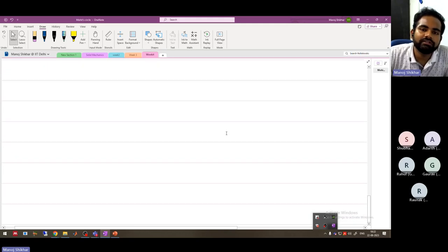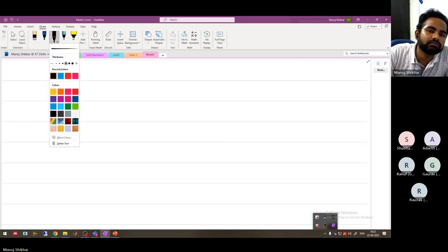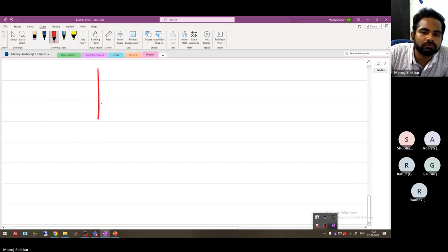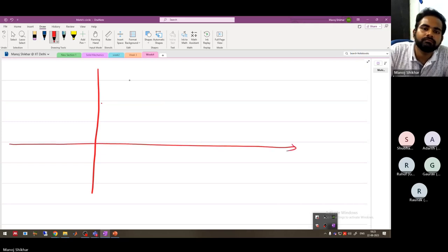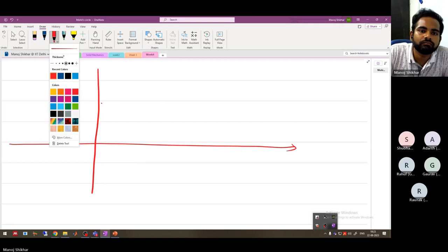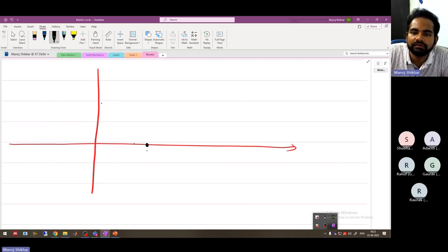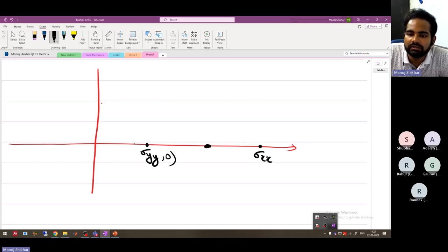So now I will represent those steps graphically here. So first we know that sigma yy is somewhere here. Let us assume sigma yy is here. We have sigma xx here. So where will be the center? It is somewhere in between. So it is on x-axis, right? So coordinate should be zero. The center is sigma xx plus sigma yy by 2, 0.